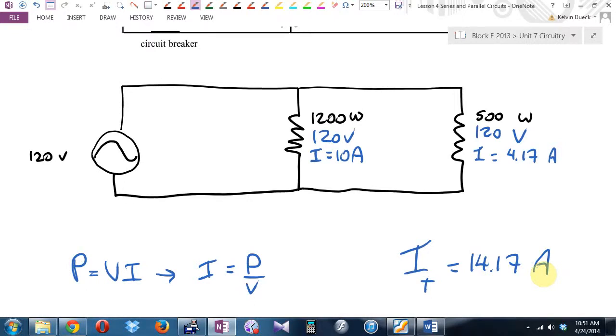In real life, because you're so close to tripping the breaker, you might find after 2 or 3 minutes the breaker breaks. What's happened is the wires have been slowly heating up a little bit at a time, and as they heat up, their resistance increases because inside the wires the molecules are moving faster and it's harder for the electrons to go through, which means they heat up the wires a bit more, which means the wires' resistance increases even more, and that might put you over the top.